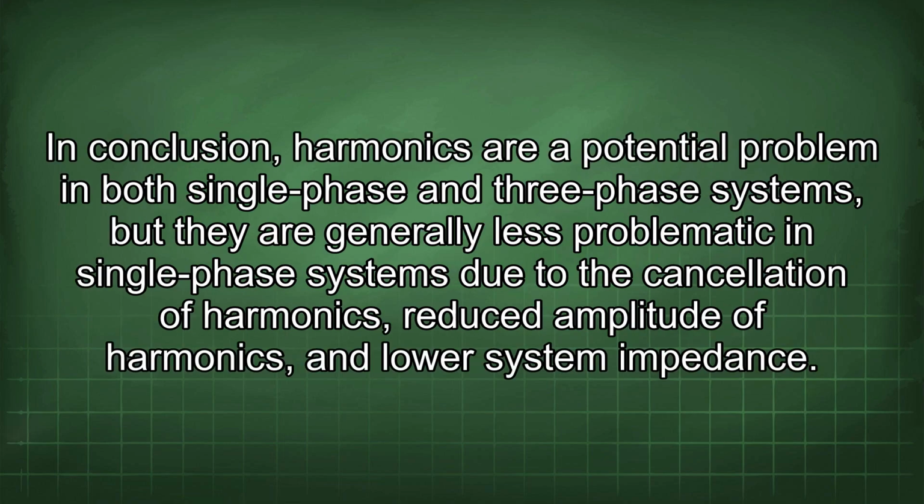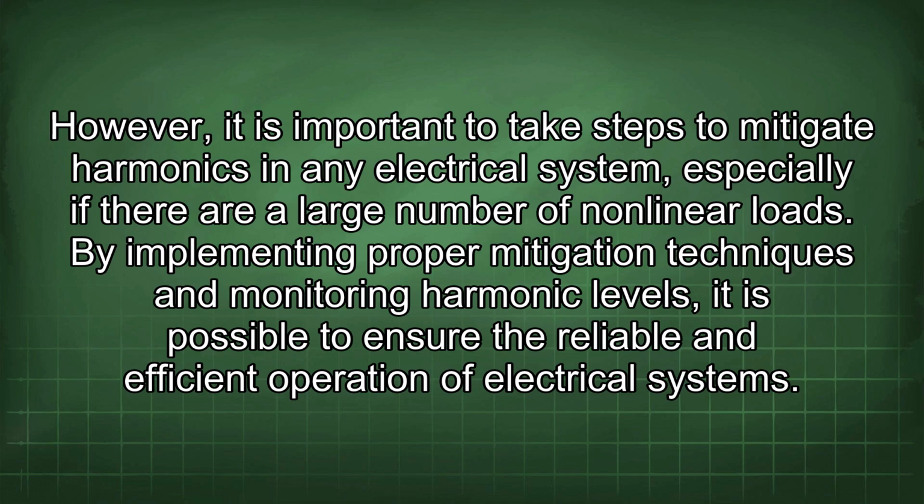In conclusion, harmonics are a potential problem in both single-phase and three-phase systems, but they are generally less problematic in single-phase systems due to the cancellation of harmonics, reduced amplitude of harmonics, and lower system impedance. However, it is important to take steps to mitigate harmonics in any electrical system, especially if there are a large number of nonlinear loads. By implementing proper mitigation techniques and monitoring harmonic levels, it is possible to ensure the reliable and efficient operation of electrical systems.